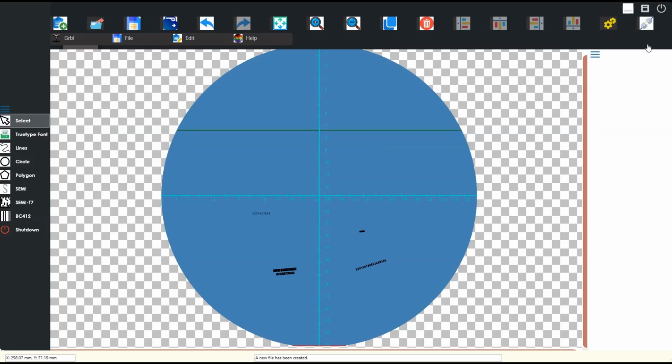To connect to your laser scriber, click the Connect button on the top menu. Choose the COM port and baud rate in the property window, then click Connect. Finally, click the Engrave button to send your design to the laser machine as G-code commands.